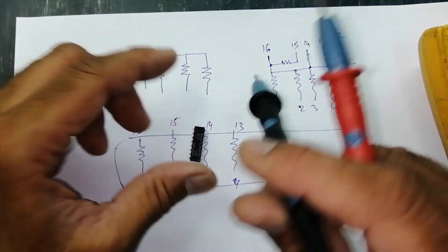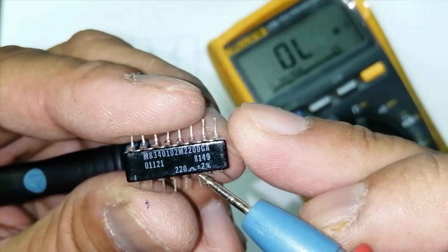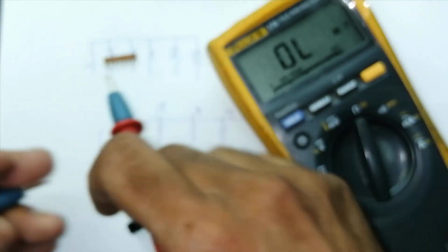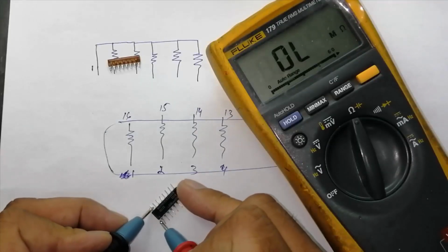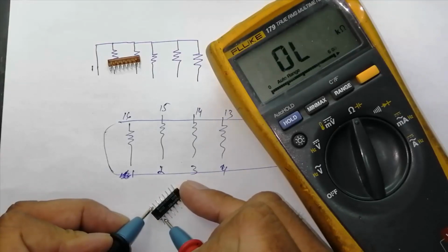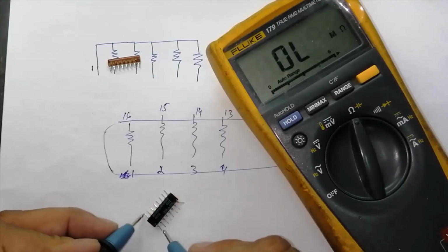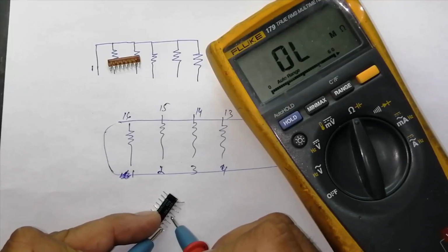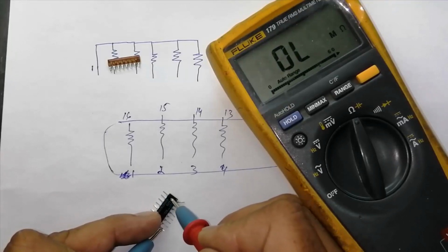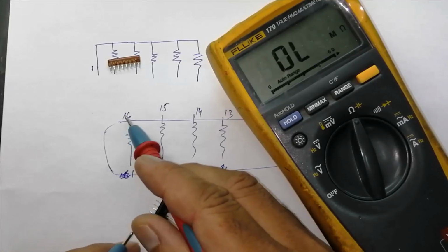And we have another pack that is called 1-to-1 resistor. So it is 220 ohm. So it will give a resistance between two pins, 220 ohm, and every resistance is independent. It has no connection with all the other pins. Every resistance is independent of each other. Pin 1 with 16, 2 with 15, 3 with 14, like this, and no resistor is connected to other pins. Just only one resistor is between these, like this here.